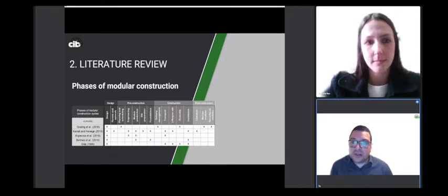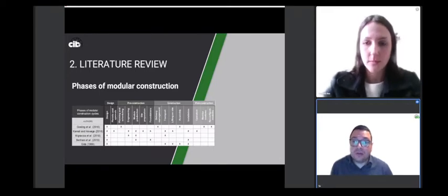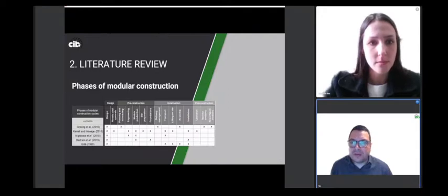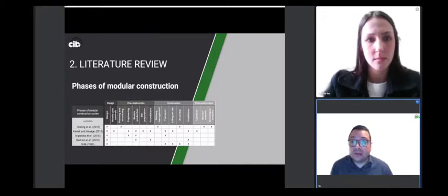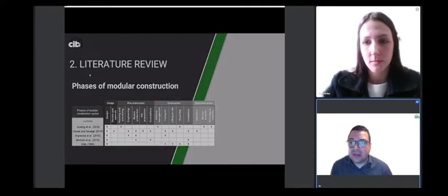In modular construction, there are two types of modules, three-dimensional and two-dimensional. Specifically, beams, panels, and finishing elements are used to manufacture 3D modules on production lines, while frames, walls, windows, and doors are used for building two-dimensional facade panels. Nevertheless, in this paper, 2D elements are called 2D modules only when they are produced off-site and transported to the site almost finished. So, the focus of this study was to investigate modular buildings comprised mainly of steel 3D modules, and the main parts are characterized below.